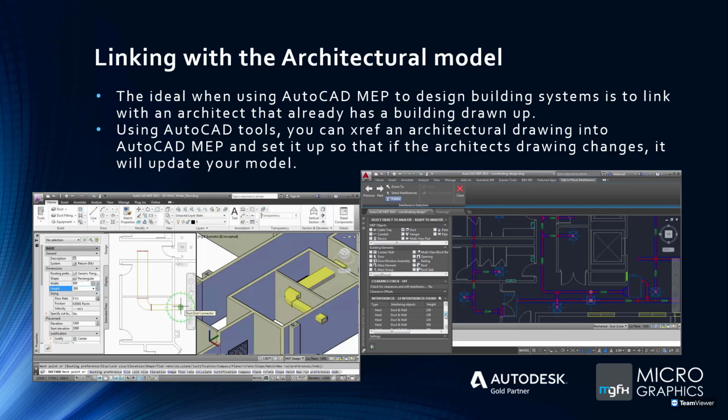Right, as I mentioned earlier as well, you can open or link in a 2D AutoCAD drawing and then use that as a background and then add your services over that. An example is on the right-hand side. There's a 2D plan where they add the ducts over that. Those ducts, the blue and red ducts, or purple, magenta, would actually have heights, so they would float above the floor plan, which is at height of 0.